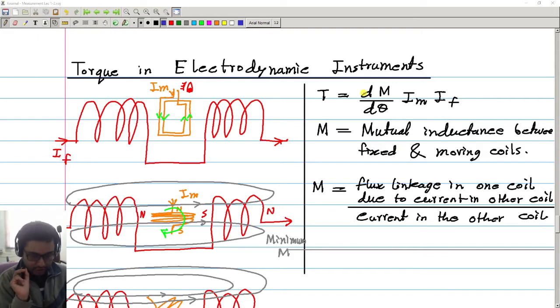Yeah, a very good question actually. So the torque between the two sets of coils at any moment, what factors does it depend on? From physical consideration, it depends on the values of the two currents at that moment, because that will tell how strong the two electromagnets are, and on the relative position of the two coils. These are the only two factors. So if these two things are given, then the torque will always be fixed.